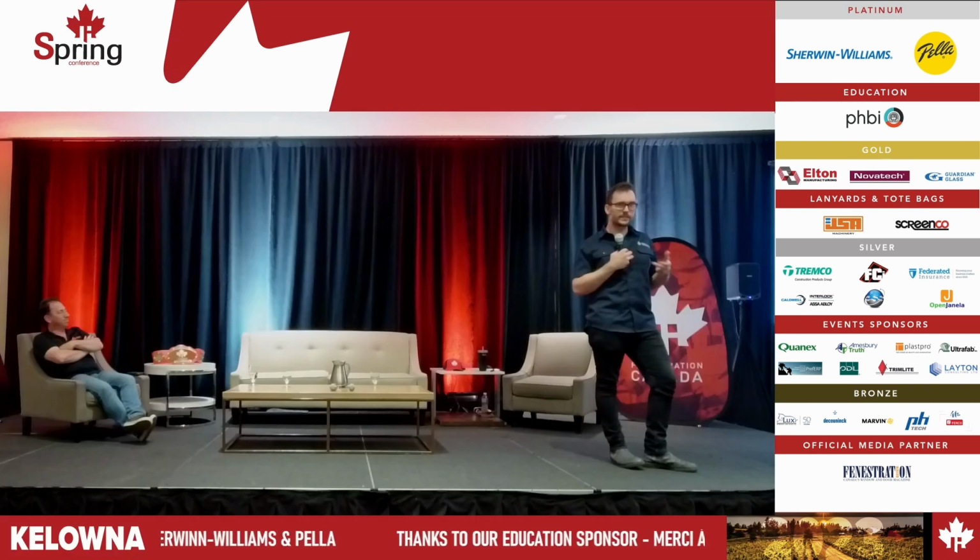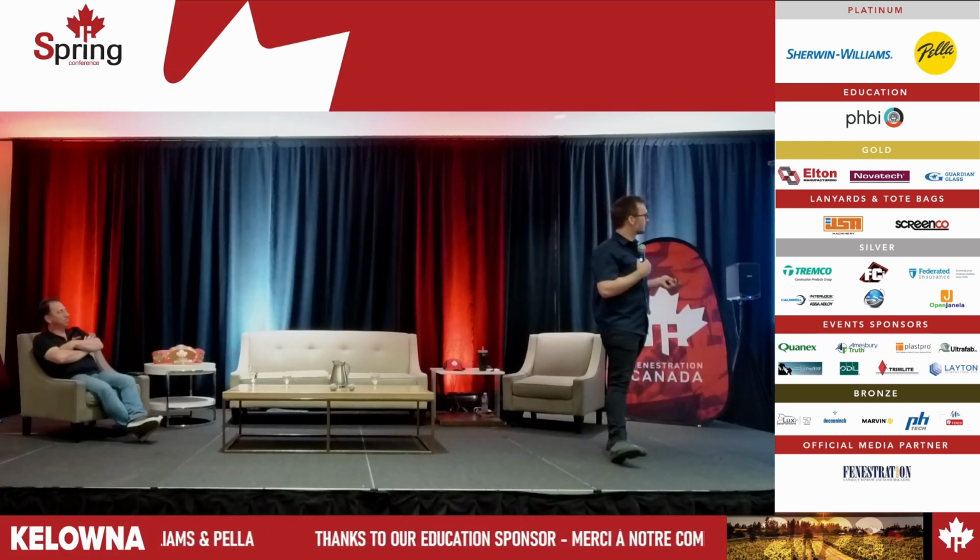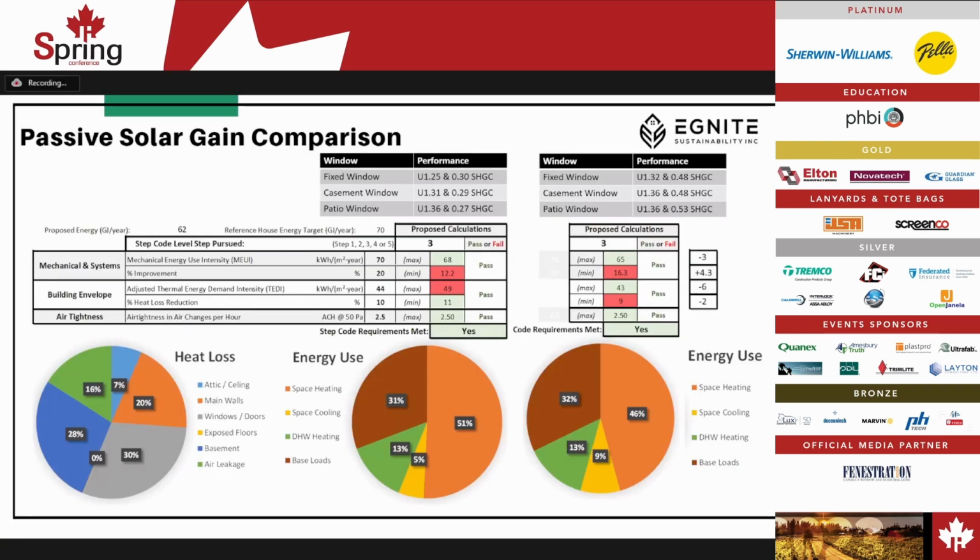So in this case, what does it do to the step code metrics? We get a better result for energy efficiency. It's more energy efficient. That's why some energy advisors are pushing towards that higher solar heat gain coefficient window. So just to quickly run through the metrics, on the mechanical energy use intensity, we're going from 68 down to 65. That's a 3 kilowatt per hour per year decrease.